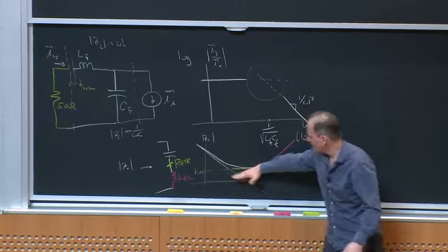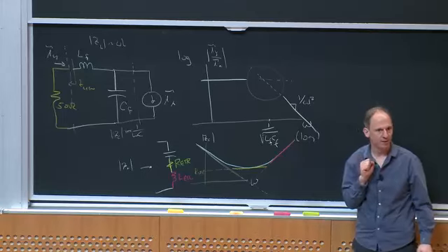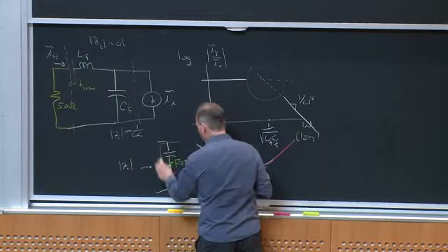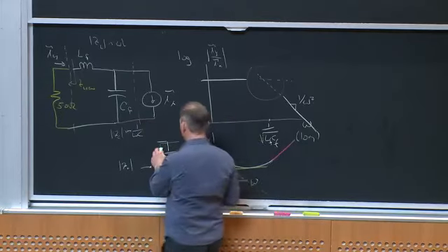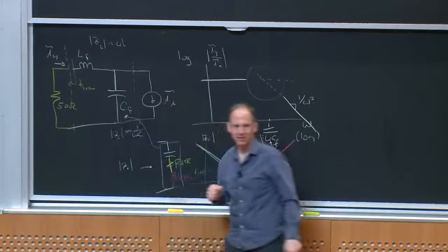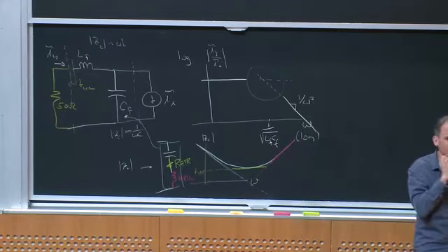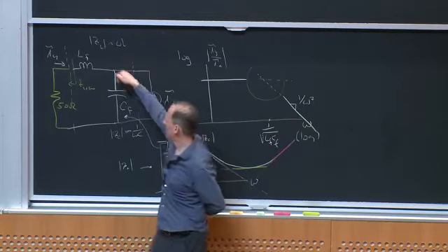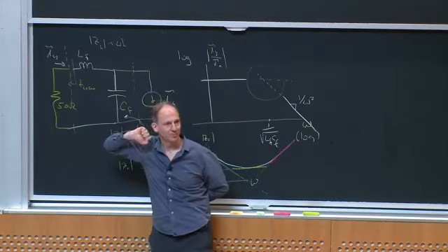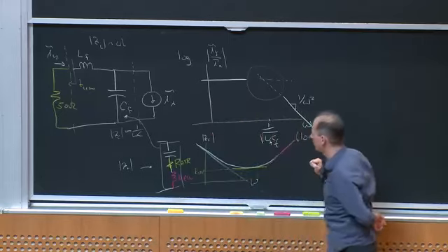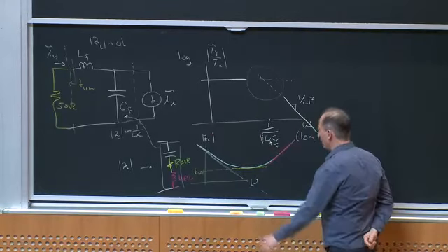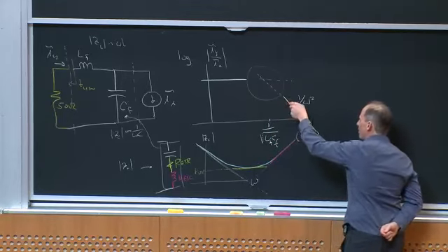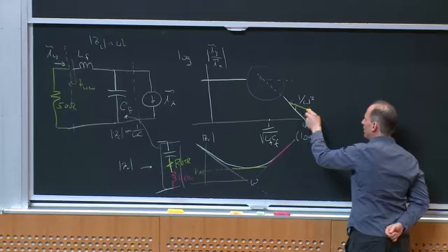But either way, you're going to get this kind of behavior. All right? Why am I harping on this? Because if I thought of this as my real element, now I plug this thing in place of my capacitor, what would I expect my attenuation to look like in that case? Well, I said it was based on the mismatch between this impedance going down and this impedance going up, right? So eventually, instead of turning into an LC filter, it turns into an LR filter, right? So instead of falling off as 1 over omega squared, it's going to fall off as 1 over omega, okay?